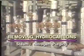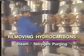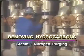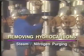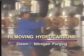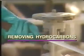One way to remove hydrocarbons from a tower is to purge the column with an inert gas like steam or nitrogen. Inert gases can strip or displace hydrocarbons off metal surfaces inside the tower and move these vapors out of the column. Water can also be used to clean out a tower.